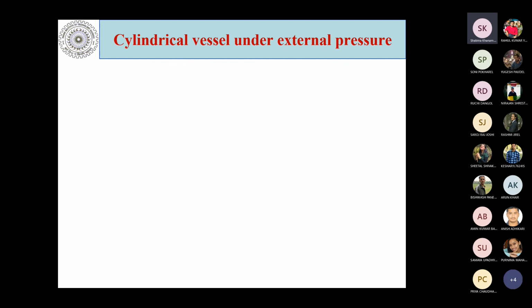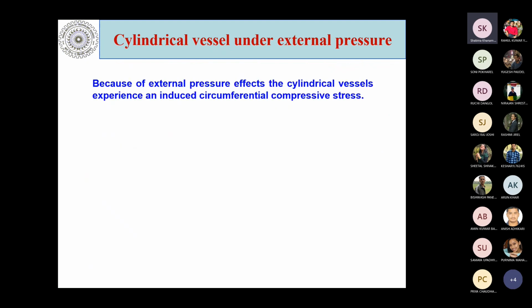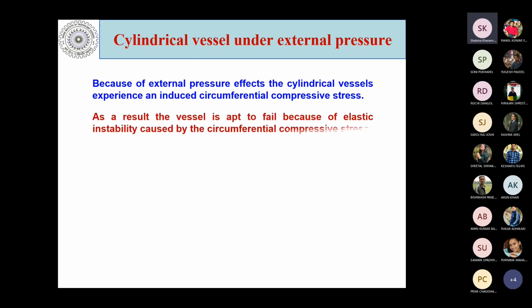Now, as far as this design is concerned, because of the external pressure effects, the cylindrical vessel experiences an induced circumferential compressive stress. As I have told you, the circumferential compressive stress is twice the longitudinal compressive stress.